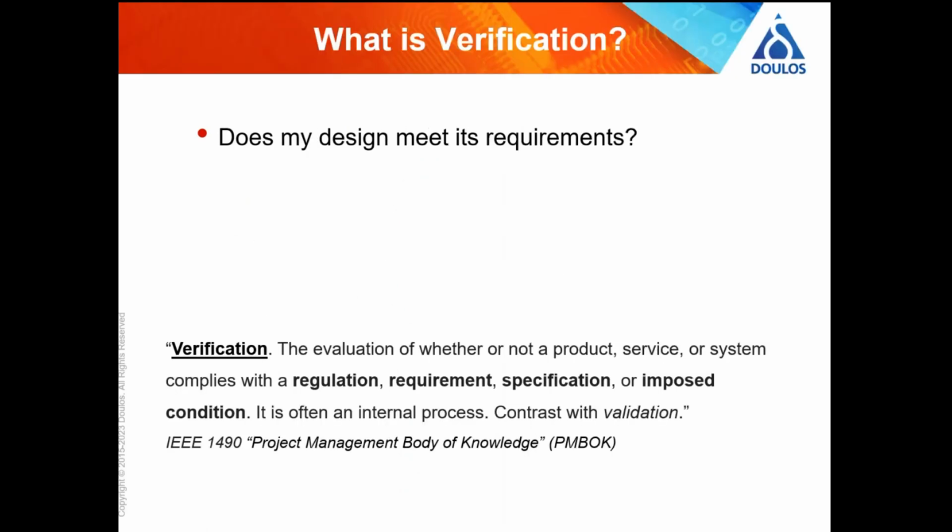So what's verification? This was touched on in Andy Bond's presentation this morning. Verification is checking that your design meets the specification, or another way of putting it, meets the previous stage of the design process. So checking that your RTL meets the specification, checking that your gates do the same thing as your RTL, and so on.